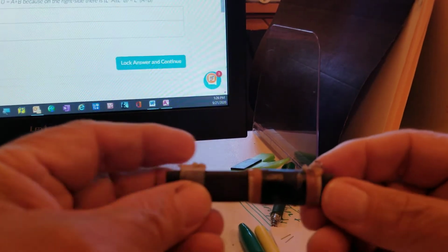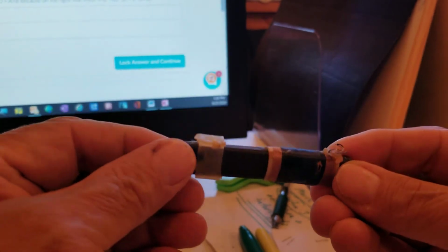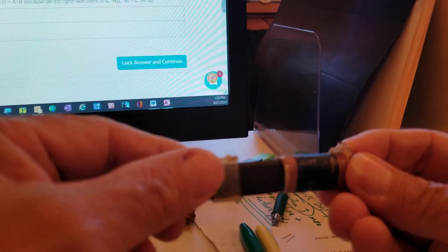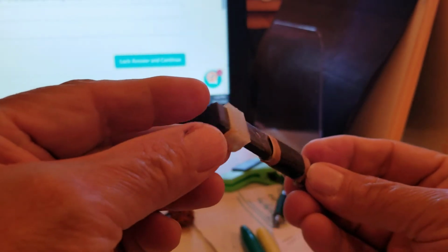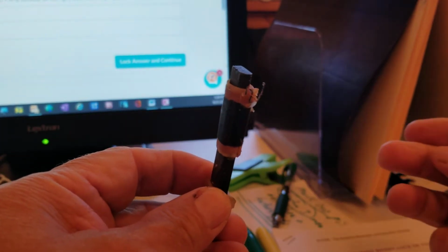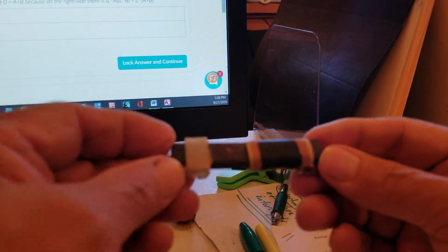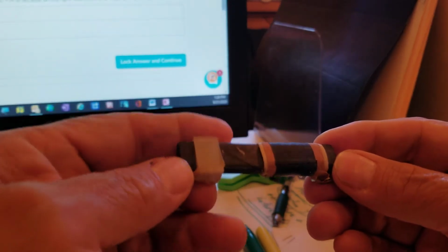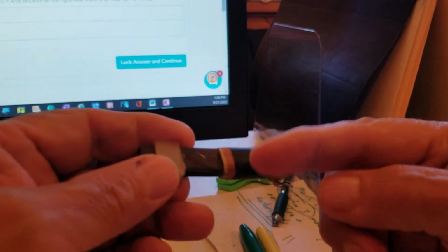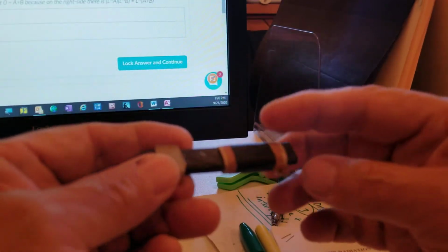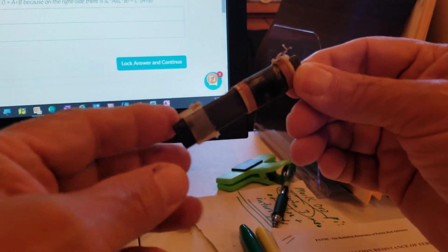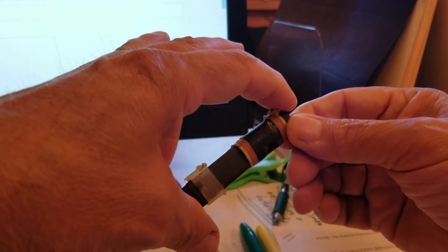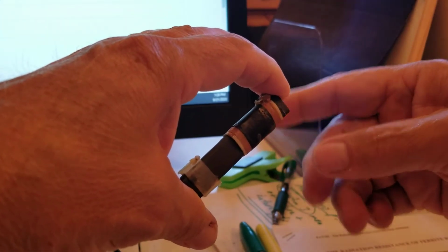Somewhere around the 1950s, there was this material invented called ferrite. This gray material right here, which is kind of a magnetic material that can tolerate high frequency changes in magnetism without turning it into heat. In the 1950s, they invented this material, and then they were able to take wire and wrap it around. This is a wire, just a coil of wire, and now this would replace the aerial antenna in a radio. So this short little piece of metal with a loop wrapped around it now makes a radio portable.